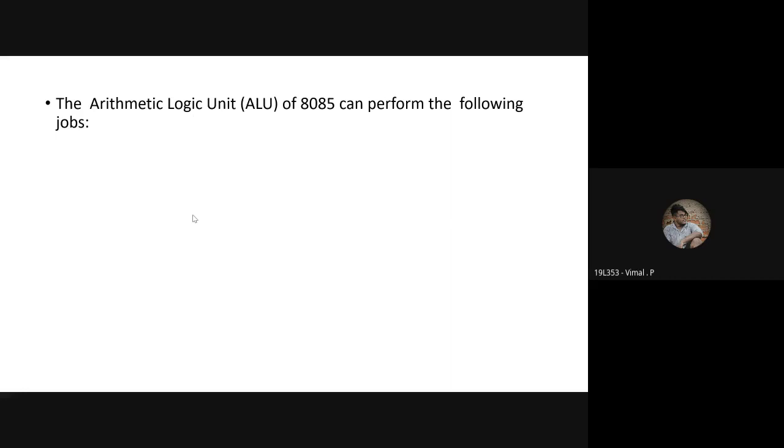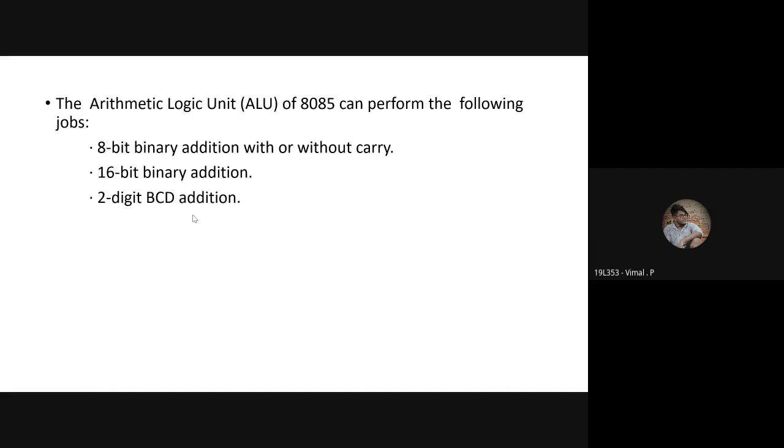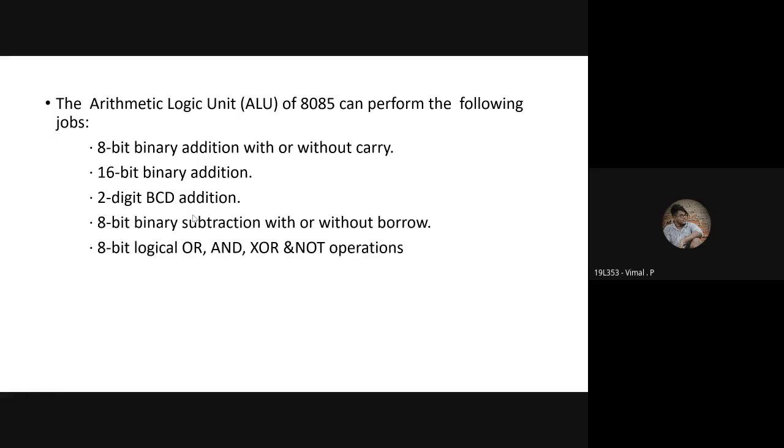The following are the arithmetic operations which can be performed using the ALU: 8-bit addition and 16-bit addition, 2-digit BCD addition, 8-bit binary subtraction with or without borrow, binary logic operations AND, OR, NOT and XOR, and bit shift operations.